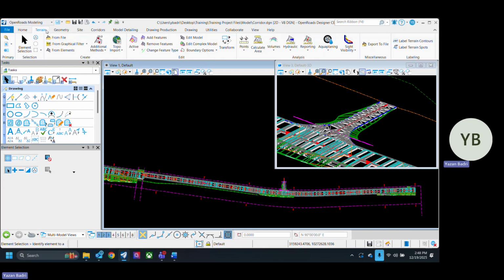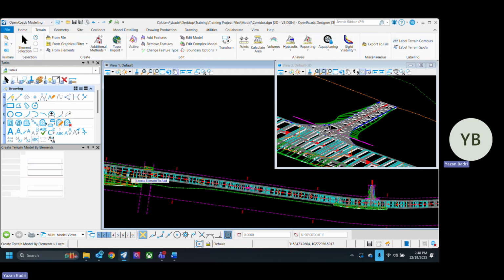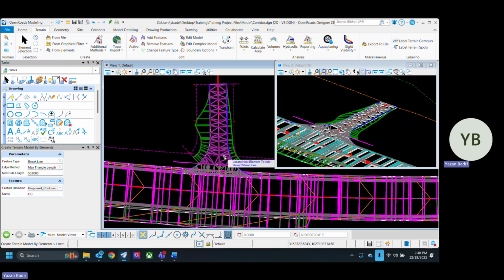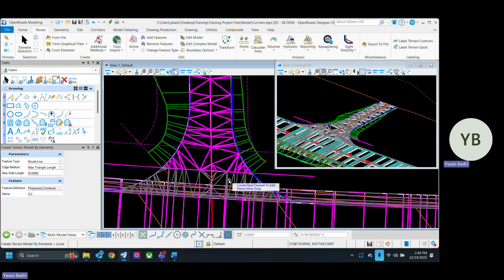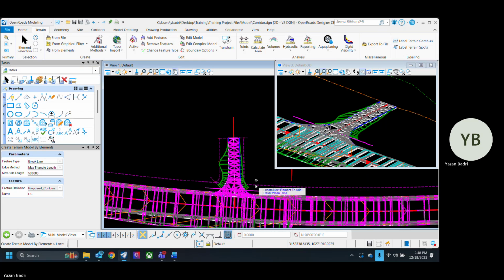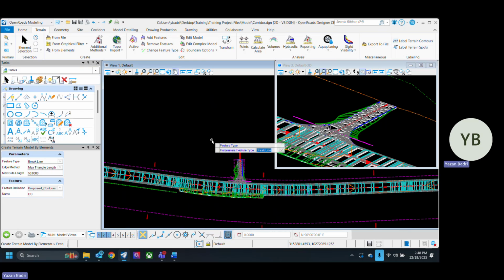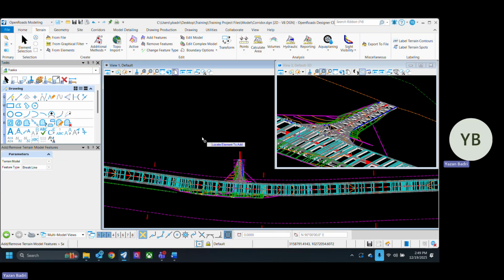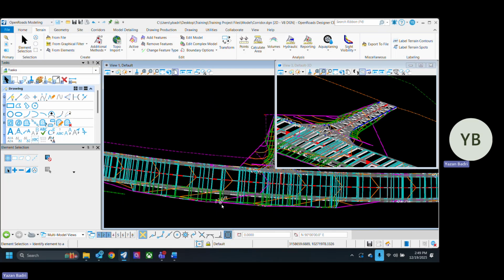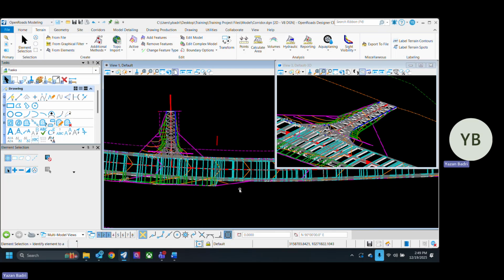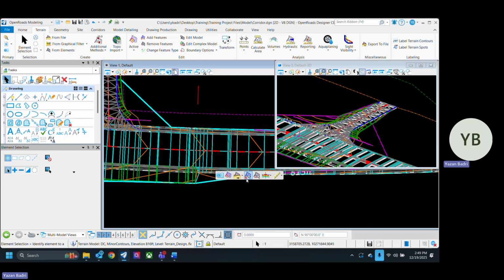And now I come to the terrain, do from elements and select that. Can also select any other meshes, such as the driveway. Set break lines, max triangle 50. And just like that, now we have proposed contours. And I have a terrain that I can click on and export to any of these formats.